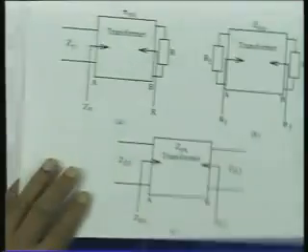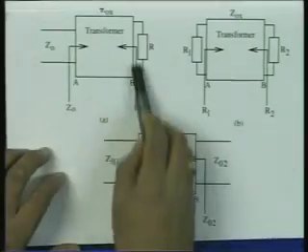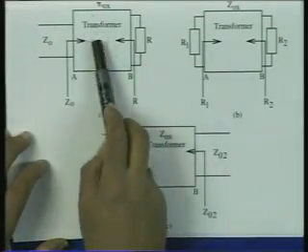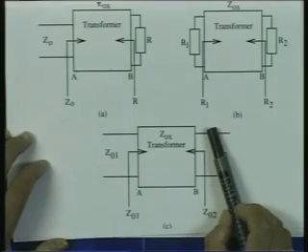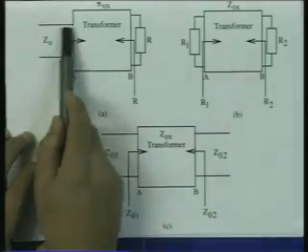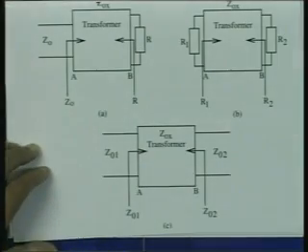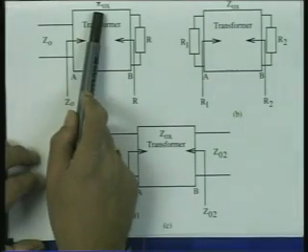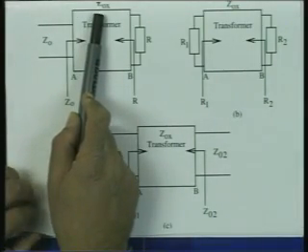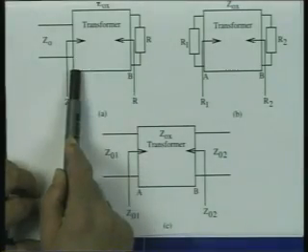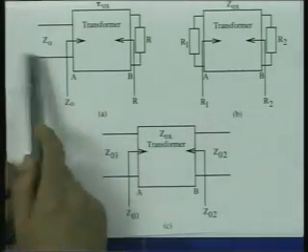So, what we are now saying is, let us introduce another section of transmission line in between, which we call the impedance transformer, and let us say it has some characteristic impedance given by Z0x, which is different than the characteristic impedance of this line to which the resistive impedance is to be matched. So, there are two parameters to be found out for the transformer. One is what should be the value of this characteristic impedance Z0x, and what should be the length of this transmission line which is introduced in between the resistive load and the characteristic impedance.